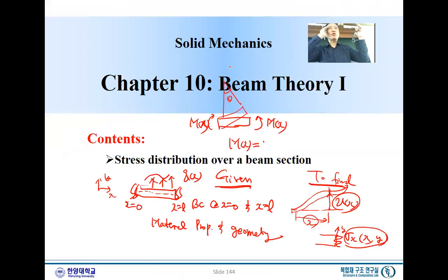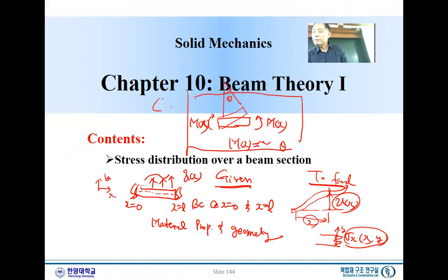This is important to understand. This is a beam, and when we have a moment, this is fixed. Look at my fingers. The finger originally was a vertical line, but when you have a moment, it has a certain angle, right? So this is the angle theta, and we want a relation between this moment and this theta. This is chapter 10, I mean, sorry, chapter 10.